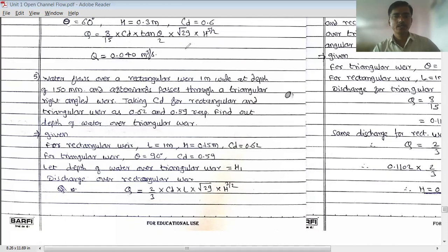A rectangular weir is given. There is a channel. Let us say this is the one channel here. Right? This is the bed of the channel. This is the water level in the channel. Let us say there is one rectangular weir here. Water is flowing over it. Right? The water level will not remain the same; what will happen at this place? The water will drop down, and you will get the diagram like this.